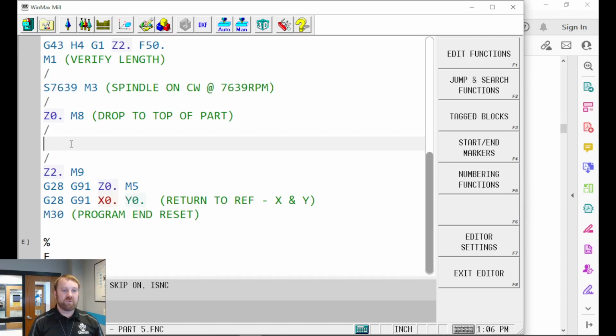Isaiah, I want to go to 0.2 here. And I want to go down a 1/16 of an inch of the 1/8 inch deep total we want to go. So give me my move first, my X or Y. Give me that first. Y 0.75. And then I'm going to ramp halfway to depth going down to 0.2. So I'm going to do a Z minus 0.0625. The overall depth's an 1/8 inch. I'm going to do it progressively as we make this little L channel here. So that gets me to P2.